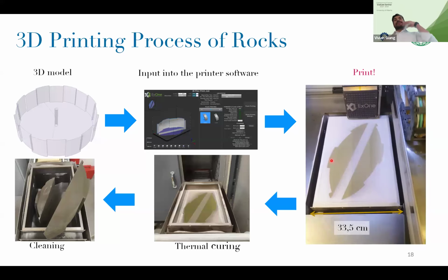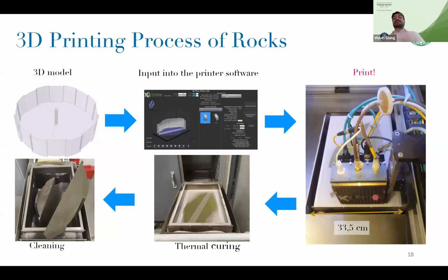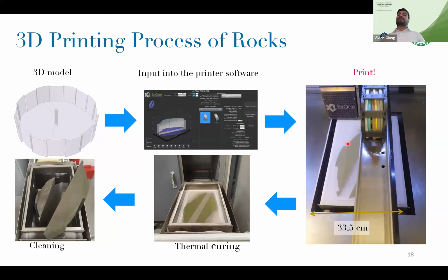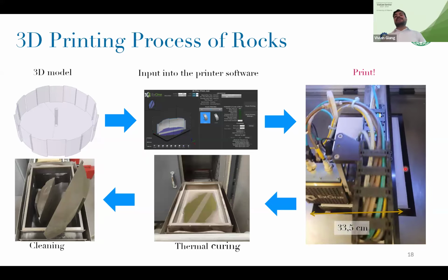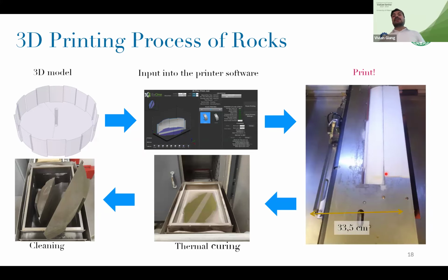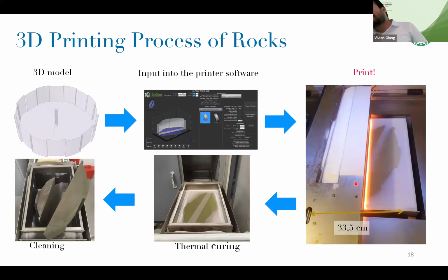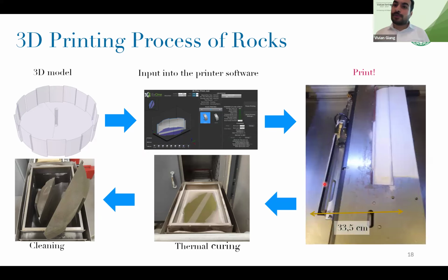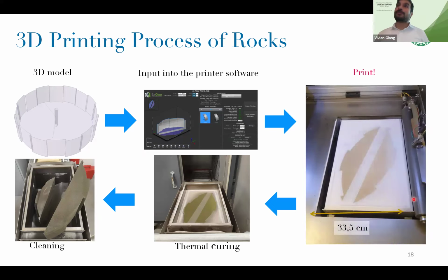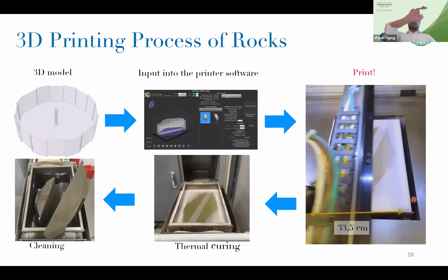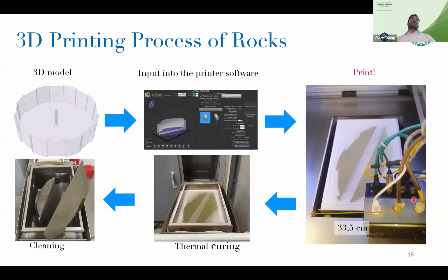Okay, so you are printing, right? You have here this white thing, which is just silica, white silica. Here you are printing your sample. And here, when the next layer of silica comes, there is a ruler, just at the front. It's moving, you see? That's the way you consolidate. You increase the density just by mechanically ruling over it.